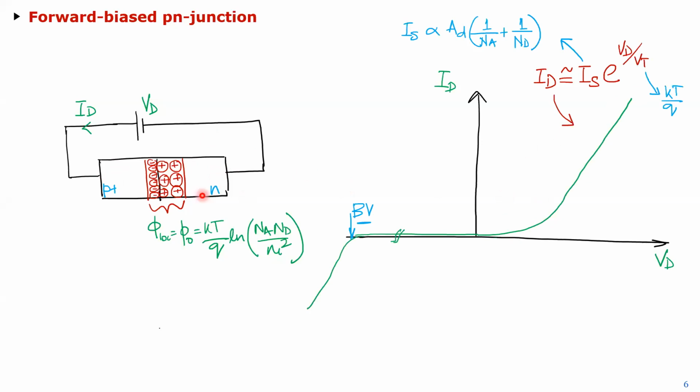So essentially what you're doing is you're first trying to fight this potential, and after that you get what's called a charge carrier concentration at the edges, and then because of both drift and diffusion mechanism, you get a current through the diode, which has an exponential relationship with the voltage across it. And this is approximately, obviously, because it's 1 minus of this.